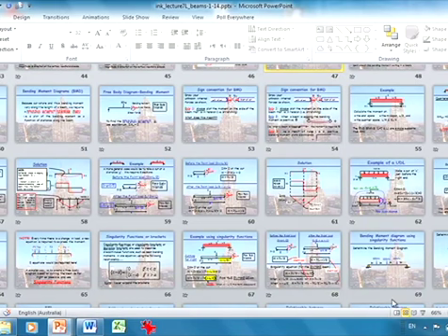Next, load it. There should be assumptions somewhere in here. What do you want to use for ultimate limit state? Dead weight plus live load. Dead weight comprised of... just go to the appendix, calculations. The final total dead load was this number. The live load, we went to the standard, AS1170, and looked in loading. It was this. So you can say, look into the appendix for all the calculations, but here is the structure with our final loads applied as point loads to each joint.